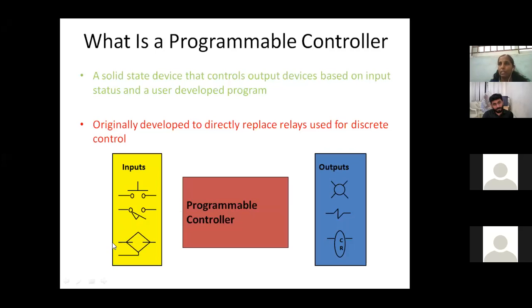So why am I choosing a PLC rather than an Arduino, embedded system, or simple data acquisition cards? It is because this input can be interfaced with any kind of supply voltage. The input device can be operated with 12 volt DC, 24 volt DC, 230 volt AC, or 110 volt AC, and that can be interfaced with this PLC directly. But as a mechanical engineer, I don't know how it functions and how I can develop a program. Simply, in your programmable controller, you can develop ladder-logic-based circuits, and based on the inputs and the logic sequence you write, you have to think it over.